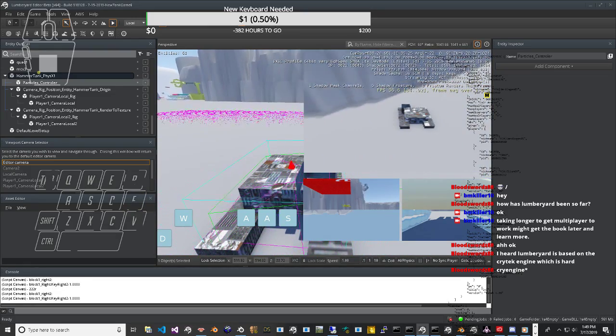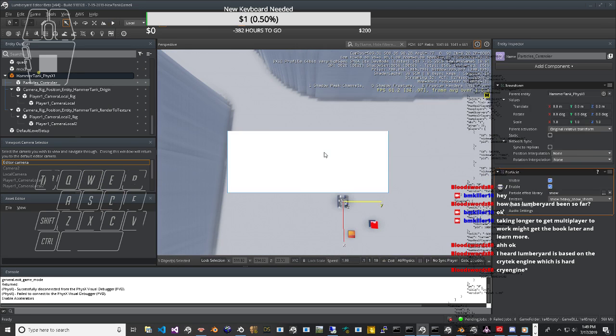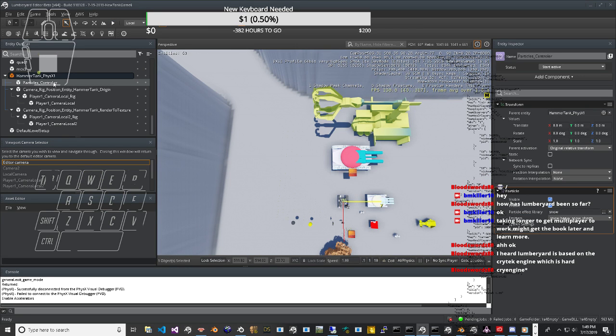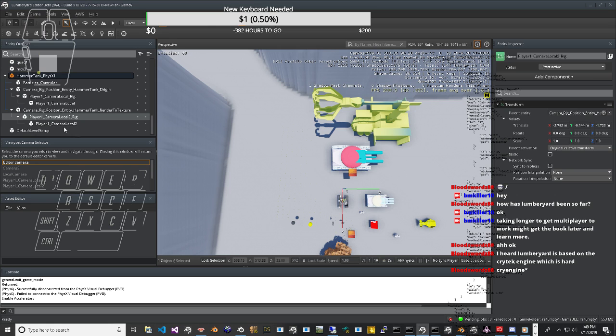In practice, we must carefully account for the algebraic signs of the camber angles so that the forces make sense at all four wheels. The usual negative camber, by the shop definition, as measured on the wheel alignment machine, will generate forces in the positive y direction on the right-hand side of the car and in the negative y direction on the left-hand side of the car. This comment makes much more sense after we've covered coordinate frames, below.